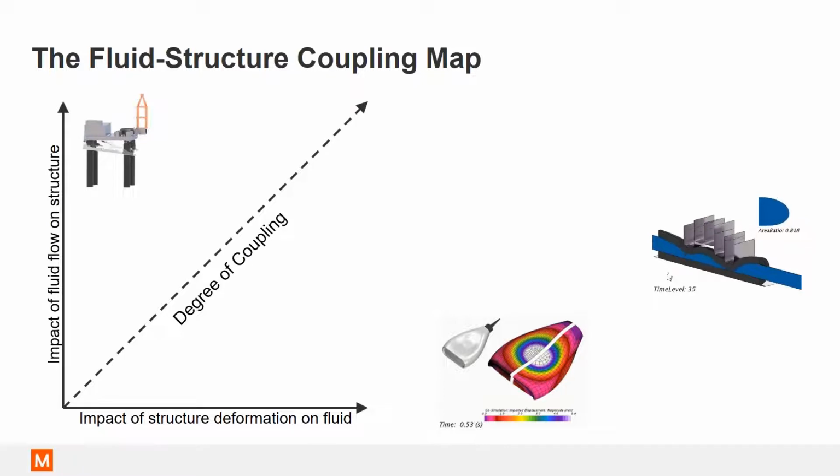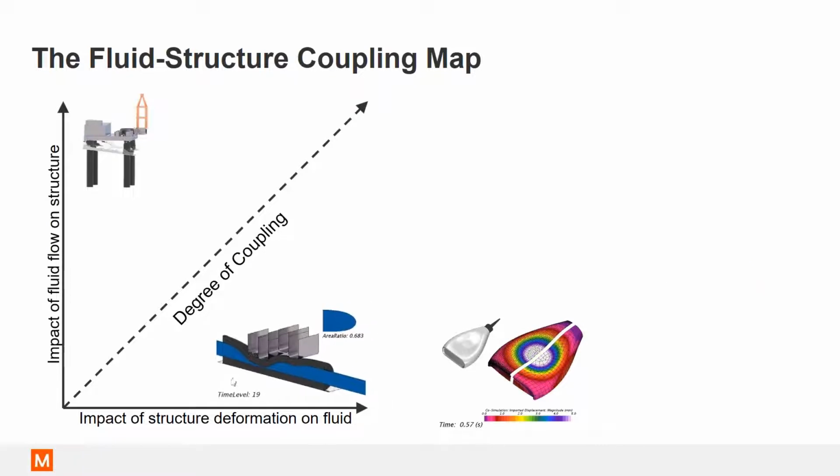The second animation here shows us a linear peristaltic pump. A series of mechanical fingers are pressing down the tube walls in a sinusoidal form. This sinusoidal wall motion generates a pumping effect. Here, the structure is not affected by the fluid pressure, but the fluid is affected by the structural deformation. This type of coupling is a one-way coupled, that is structure independent, fluid dependent.